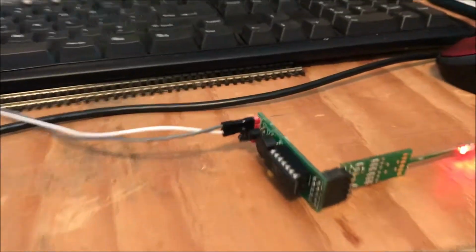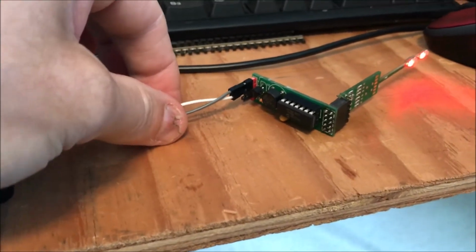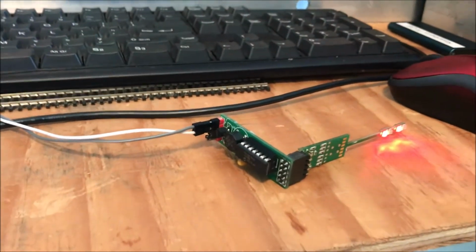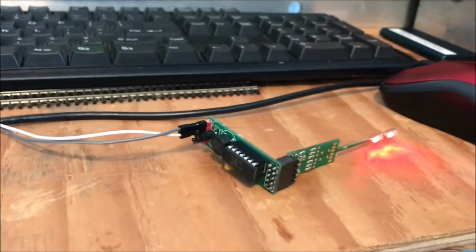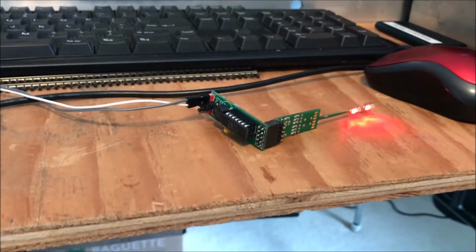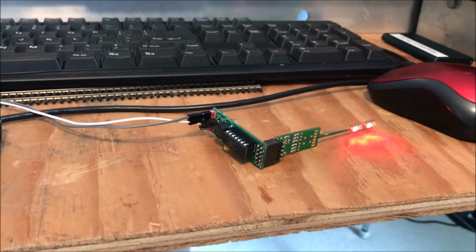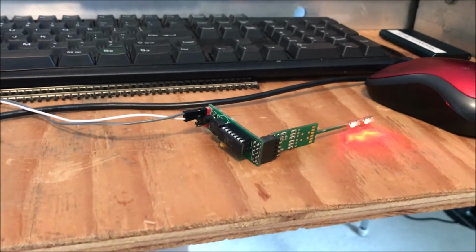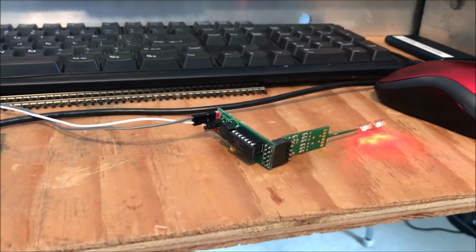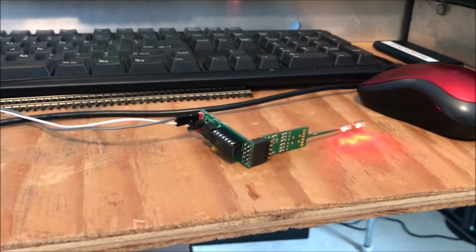What was neat about that is you can power it directly from the track. You could just connect these 2 wires to the DCC bus. So it's very easy, when you have a lot of signals, to wire them to each other. And if you ran a separate accessory DCC bus, what's good about that is that if there's a short on the track, these lights would continue to work because they have a separate bus. So that was another implementation that I did. But anyway, I really liked that, and I enjoyed that for the longest time.